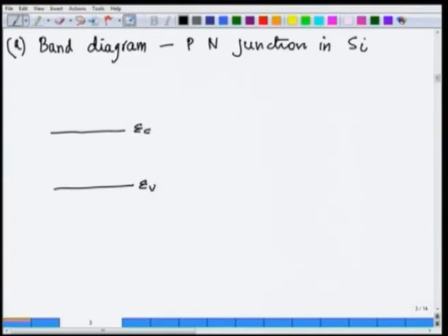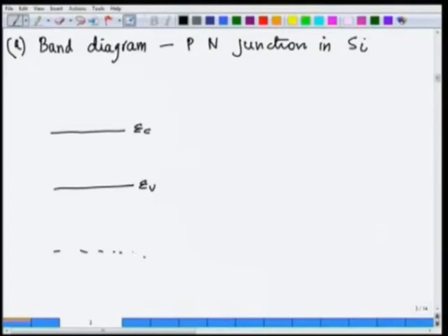Now we are going to choose a reference energy. In lecture number 16, you will recall we had chosen different kinds of reference energies. In lecture number 16, where I was talking about donor levels and acceptor levels, I was saying that because energies always appear in difference, you will have some energy minus another energy, and hence what reference you choose cancels out, but nonetheless all energies must be measured to a common reference. And in that example, I said let us choose a reference arbitrarily, reference energy somewhere here as 0. Then I said okay, let us move on and choose this point as 0 energy, let us choose EV as the reference energy, etc. This is what we had done in lecture number 16.